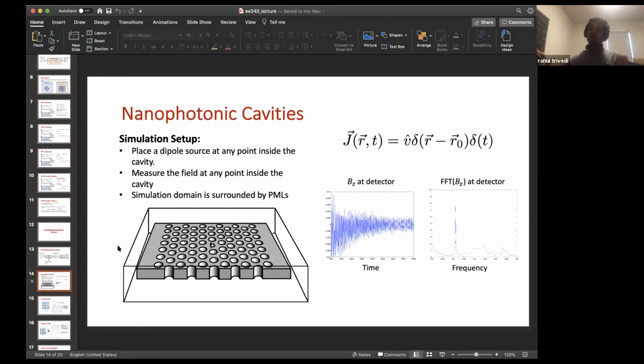This temporal width is also going to inform what the discretization is going to be. You can't really simulate a dipole source which is narrower than the delta T of your simulation. So you have to keep in mind that the time width of the dipole source that you're putting in should be at least maybe one or two orders of magnitude larger than the delta T that you're using. Oftentimes I've had people show up with results saying my simulations are giving me 0. That's because their source is smaller than the delta T of their simulation. Obviously you're going to get a 0. So you have to be careful about these things.